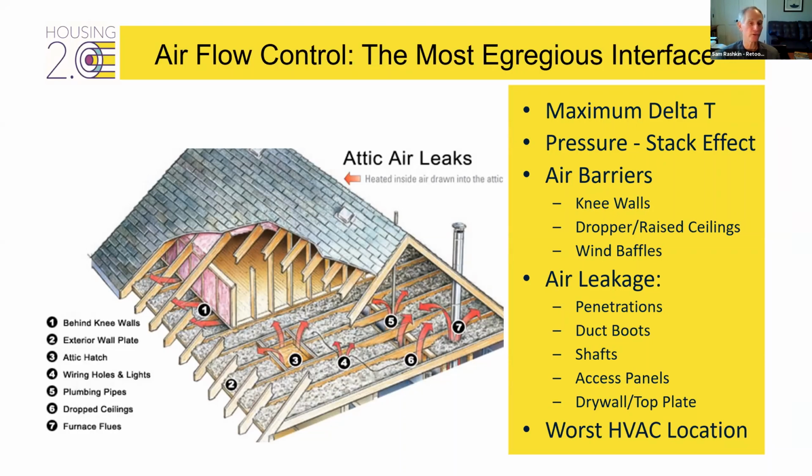This is the absolute worst location for HVAC, and you go west of the Mississippi or the western region of the country, and for some reason we're still putting HVAC air handlers and duct systems in attics. This is just not going to get the job done for a zero carbon building. We have to address this.